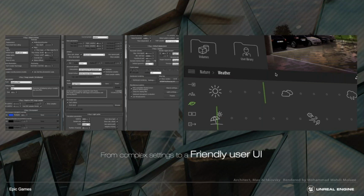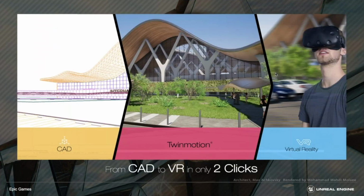With that in mind, we have also created what we call the direct link. The direct link creates a bridge between ARCHICAD and Twinmotion. Directly from ARCHICAD, once you have installed the direct link, in just one click you send the data to Twinmotion. In Twinmotion, you can start to be immersed inside your project. You can start to change things, add some vegetation, add some entourage. And then from Twinmotion, in just one other click, you can switch to virtual reality.